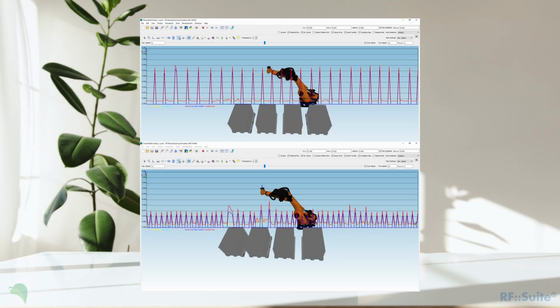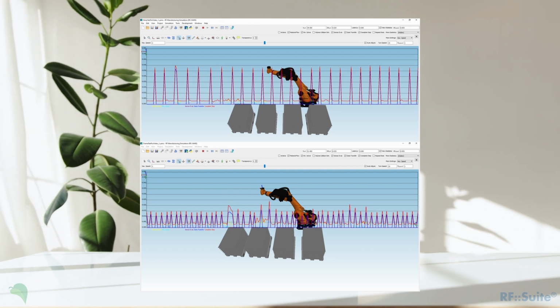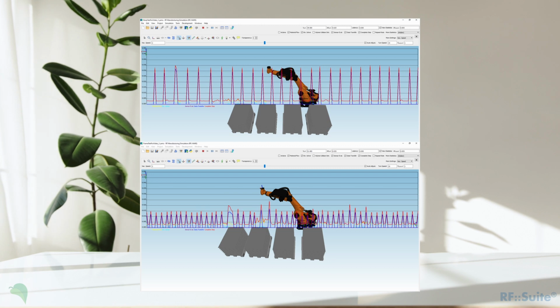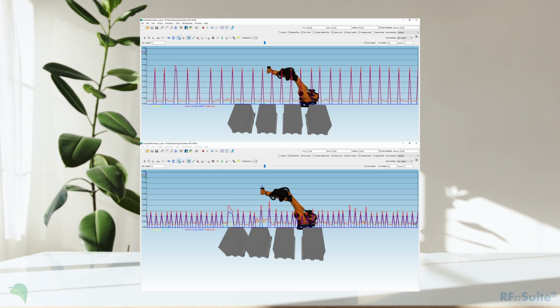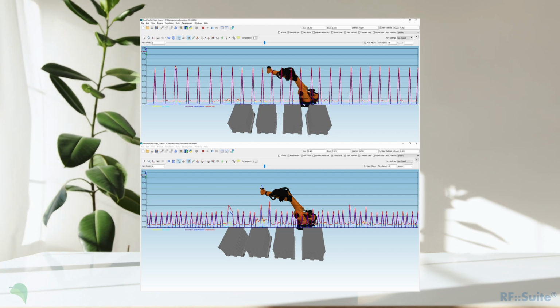Performance optimizations of up to 30% can be achieved with the help of frames. Since the frames are not part of the simulation, the optimization has a positive effect not only on material flow, but also on kinematics and transfer. Frames that are still needed as kinematic links are automatically created as bodies, and frames can be converted to bodies at any time. The example contains approximately the same number of positions, only once with frames and once with bodies. There's no functional limitation here.